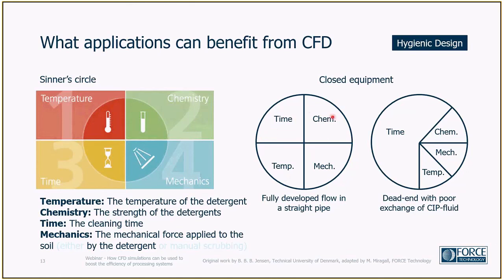And on the right hand side here, we have the straight pipe but with a dead end, and this is giving a poor exchange of cleaning in place fluid in the dead end region.